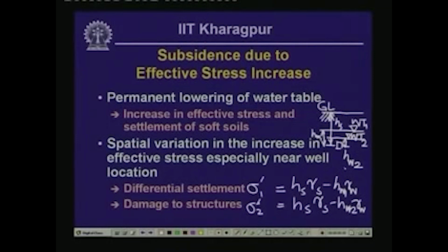So the increase of effective stress is going to be non-uniform depending on the distance from the location of the water well, and this is going to trigger differential settlement within any facility that is constructed within the zone of influence of the water well,